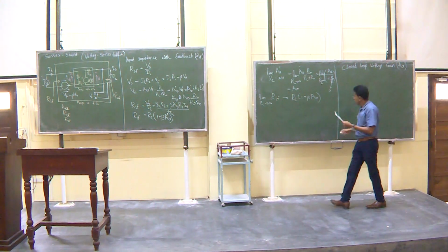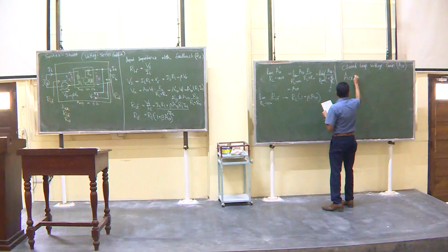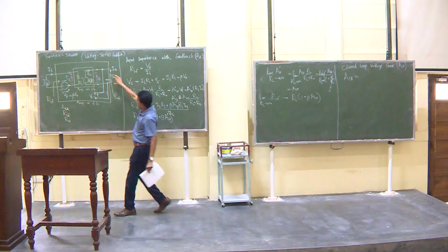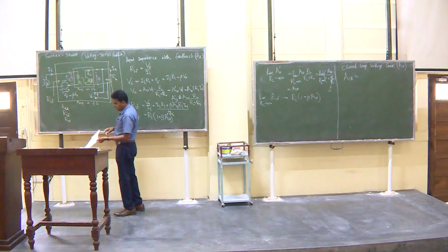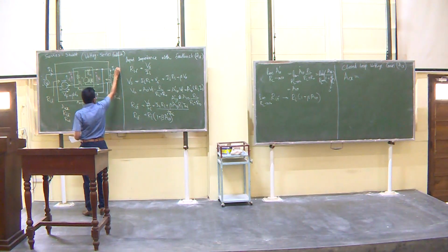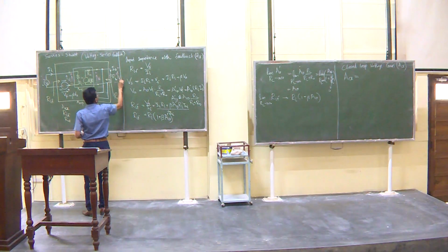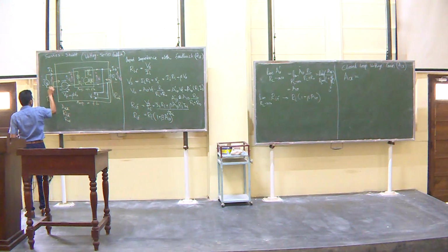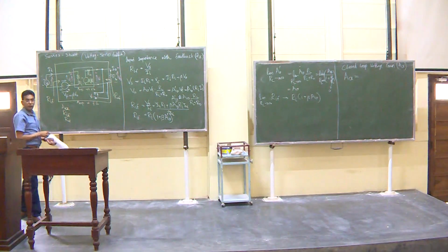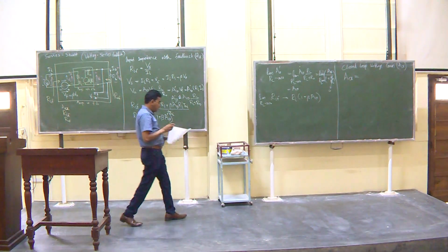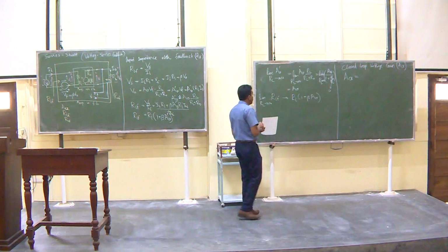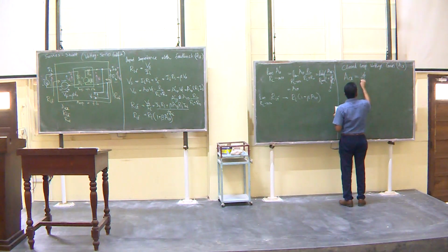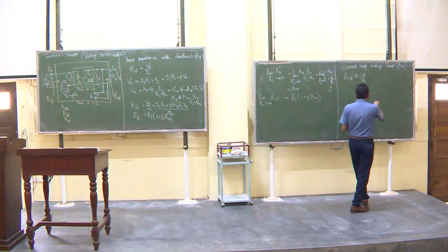ACL. How do we define ACL? It is the output of this feedback amplifier, that is V out, which is basically the voltage appearing here. There is nothing in between. And the input here is Vs. So ACL is V out divided by Vs. So, what is V out?